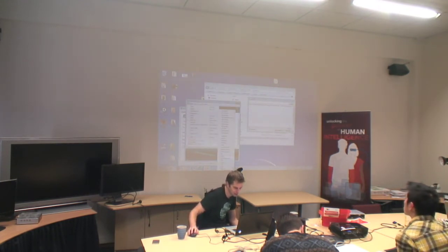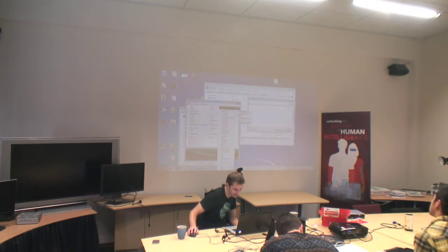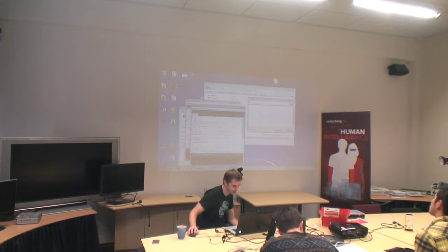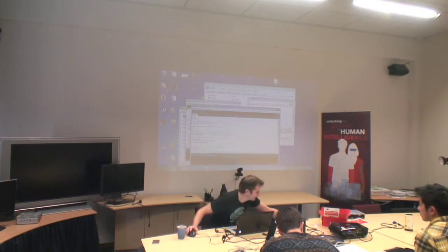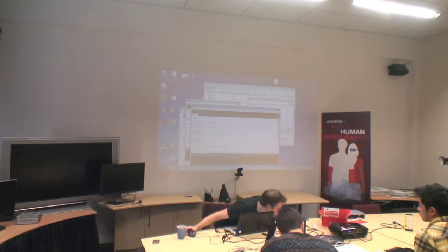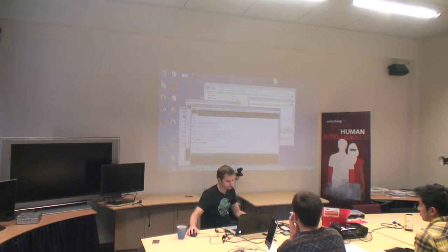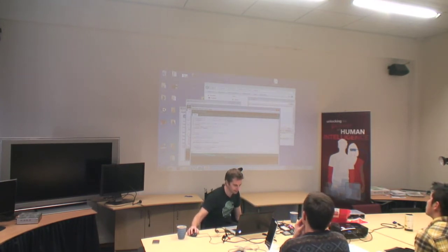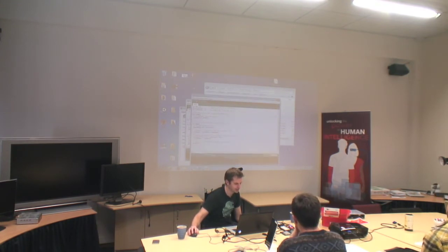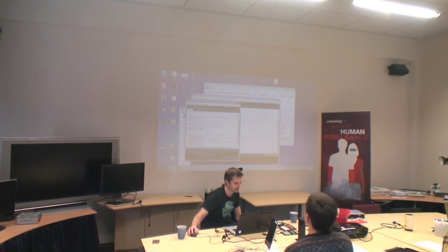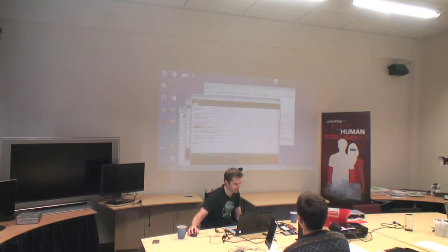So we'll just show a quick example. Oh, fade, that's the one I wanted. So here's an example here. LED on pin 9. And if I run this one, you'll see down here, instead of our digital write that we were doing before, where we just tell it a pin and a value, now we have analog write.